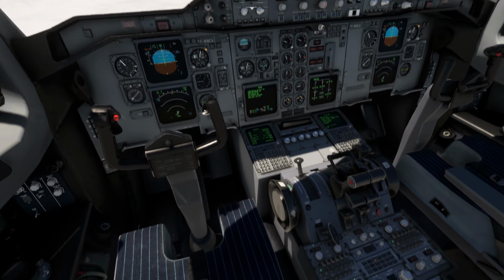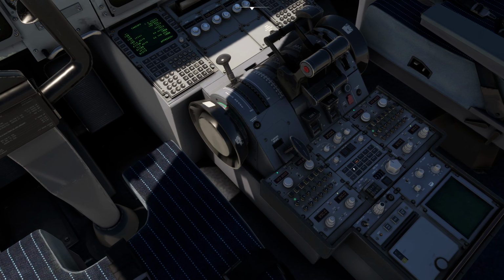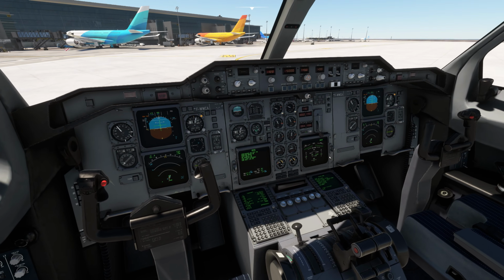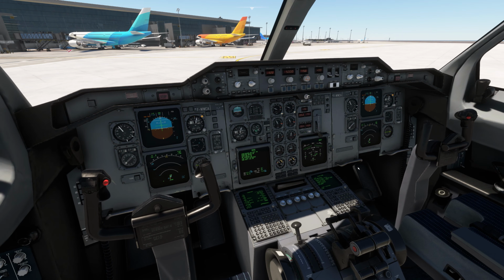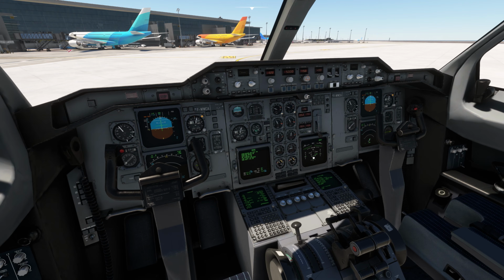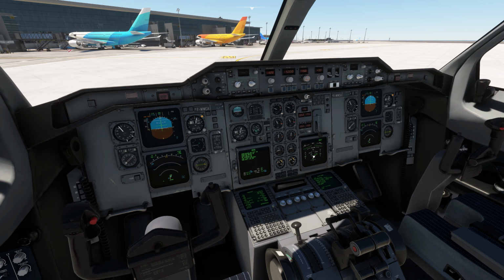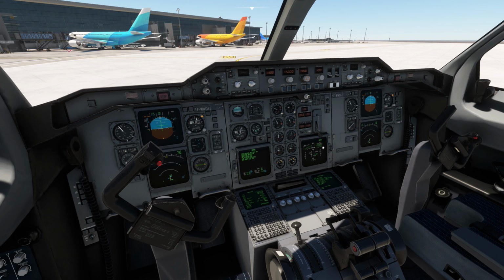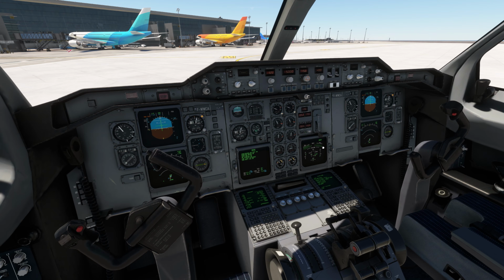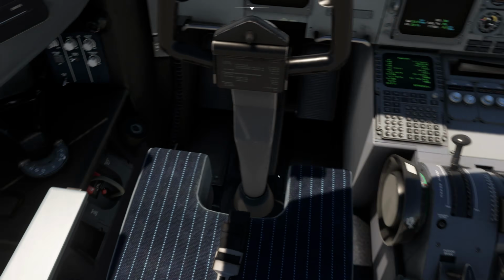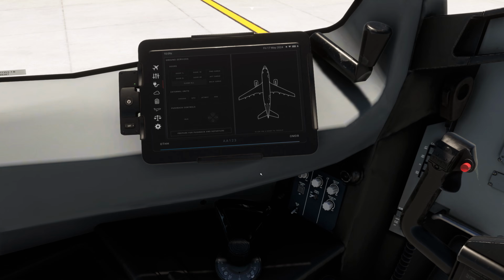Now just make sure everything is good and do the flight control test. Just go over here and press this button, and on the eCam you will see the flight controls. Just move the yoke forward and you can see the elevator working. This arrow is moving, and just pull it back as well and then move it towards the right. You can see the ailerons are also working, and plus the rudder, it's working.